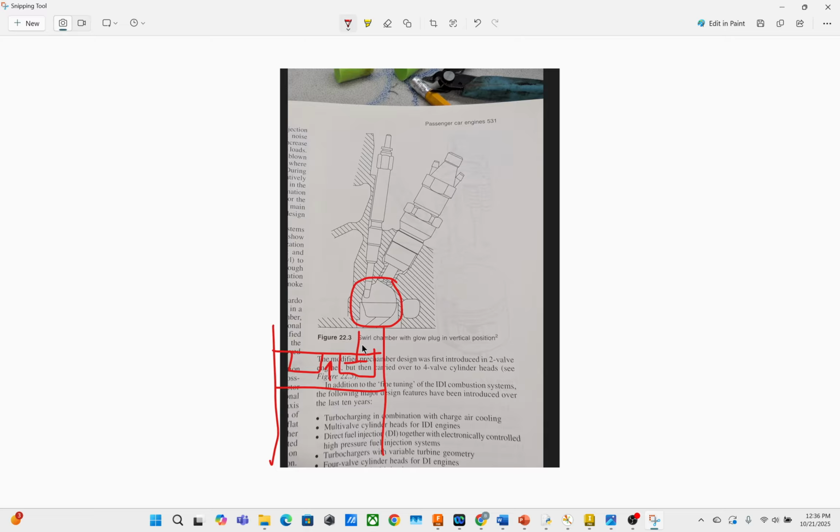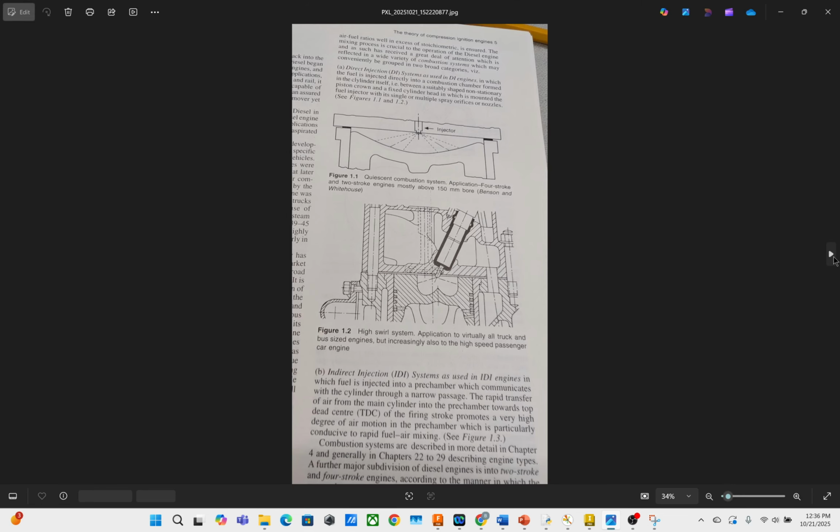Huge advantage, because basically if you look at an 1.9 liter TDI from Volkswagen, which is here, this is what everyone does now, but you have something that I don't like, which is a situation where you have a direct injection engine and it could collide, and it's only connected by a belt. So if the timing belt breaks, the chances are you're going to crater the whole engine. Okay, so what are the options here?